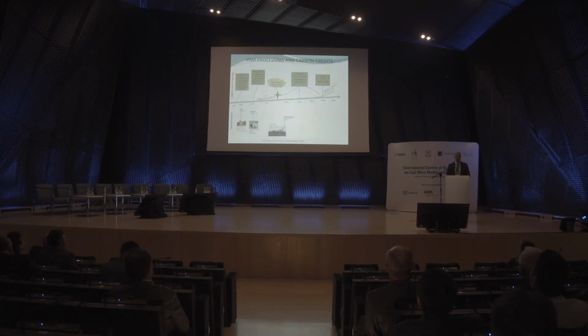So looking at the trials of VAM installations, the first one was actually in 1994 in England. A small unit that showed that it was possible to operate an RTO on VAM. Then, 3 years later, there was an Australian trial, also a small unit, showing that it was possible to use the energy developed when you oxidize VAM to create steam.